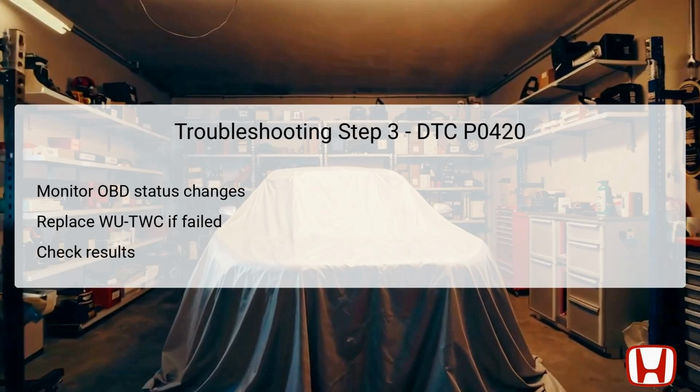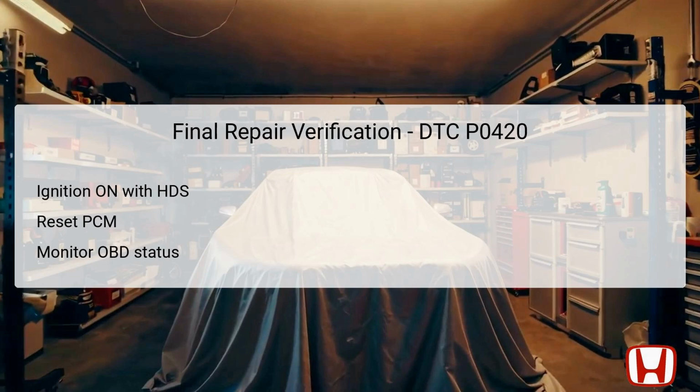proper emissions functionality. After completing the replacement, it's necessary to conduct a verification test to confirm if the issue has been resolved. If the HDS indicates a passed status, troubleshooting is complete and no further action is necessary at that moment. However, if further testing is required due to executing or out-of-condition statuses, the same testing conditions must be maintained to yield definitive results. After performing repairs or replacing the catalytic converter, final verification of repairs is imperative.